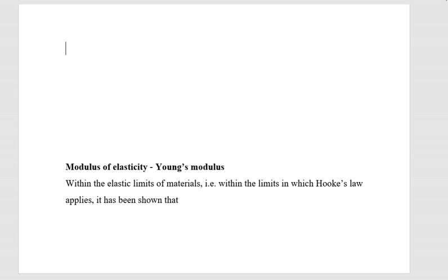Today we once again meet to discuss some more concepts of mechanical engineering science. In our past lecture, we are going to review what we talked about, and we talked about stress. And we said stress is given as the load per unit area: load over area of cross section. This we said can be in newtons or kilonewtons, giganewtons or meganewtons.